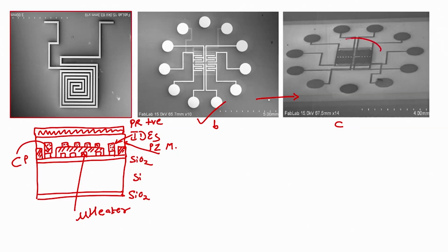I want to create this particular chip, you see here, right. The next step, we all know, is to soft bake it. Soft baking can be done at 90 degrees, 1 minute on a hot plate.